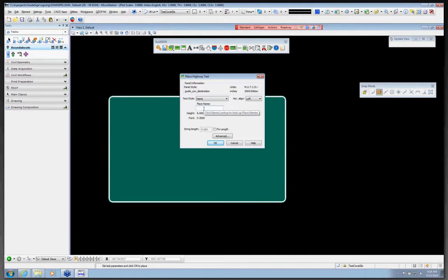At this point, if you're not familiar with signs, you would find this information through your MUTCD, and certain signs, if you're doing it for the Florida Department of Transportation, are dictated through our traffic engineer manual for size of lettering to start with. We always want to start with a larger lettering type for better visibility. In this case, the 6-inch is the minimum height.